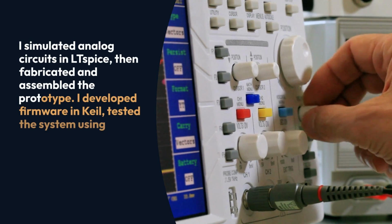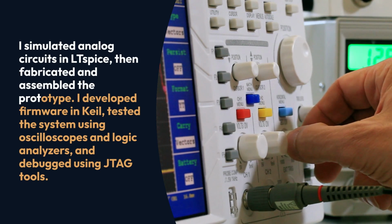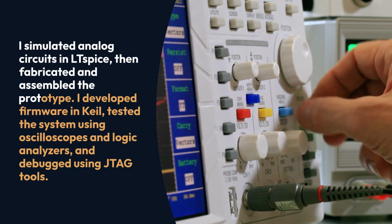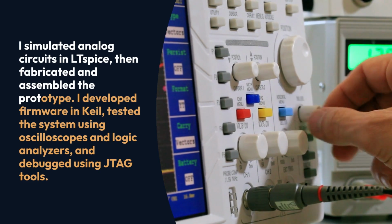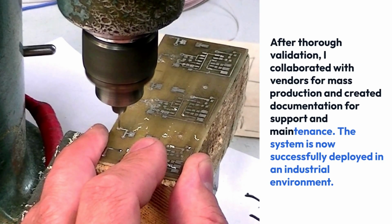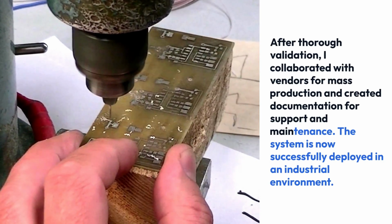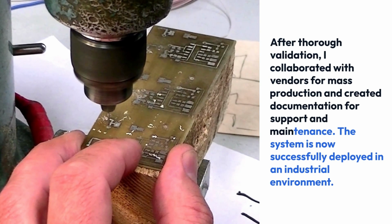I simulated analog circuits in LTspice, then fabricated and assembled the prototype. I developed firmware in Keil, tested the system using oscilloscopes and logic analyzers, and debugged using JTAG tools. After thorough validation, I collaborated with vendors for mass production and created documentation for support and maintenance. The system is now successfully deployed in an industrial environment.